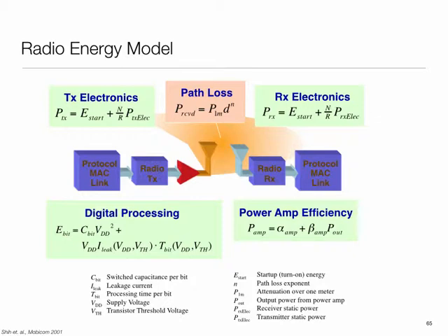So there is going to be a term which depends upon the startup cost of the radio. It's kind of rebooting the radio, and if it needs to register or synchronize with a base station, all those kinds of things, there's going to be some constant term that I'm going to pay. Then I'm also going to pay some actual transmit cost, which depends upon that plus whatever the electronics is consuming.